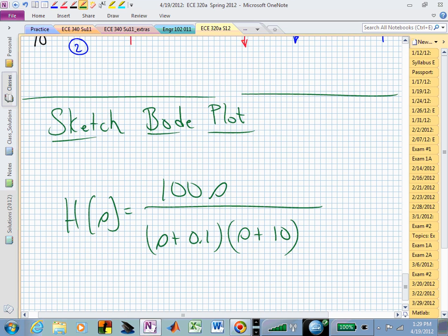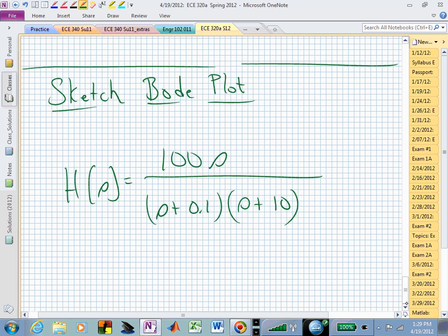But if you said, okay, now for small frequencies, replace this with j omega. And now at small frequencies, that's small. At big frequencies, it's huge, isn't it? So it's now looking like this to you guys. It looks small at low frequencies and then bigger at high frequencies. So that's what the 0 at the origin is doing. It attenuates low frequencies and exaggerates or amplifies high frequencies. Is that making sense?